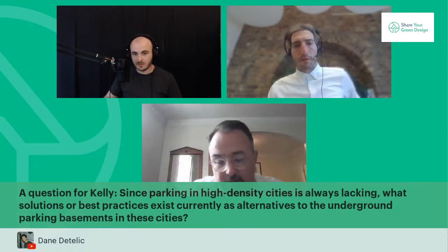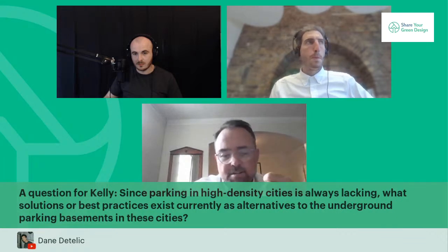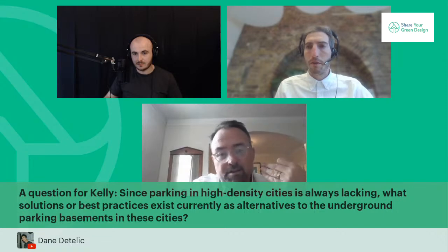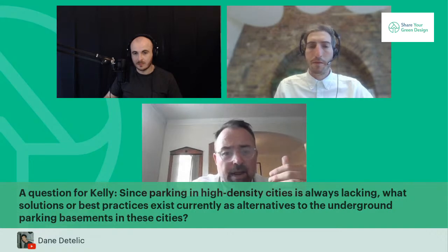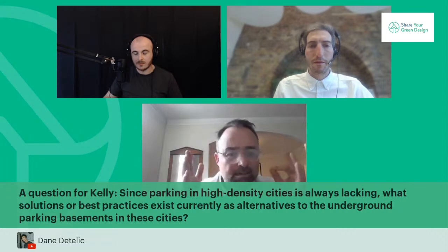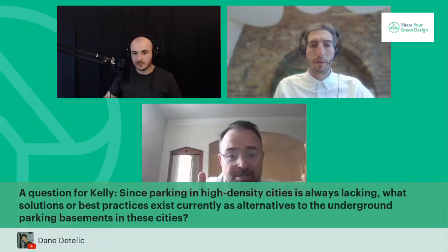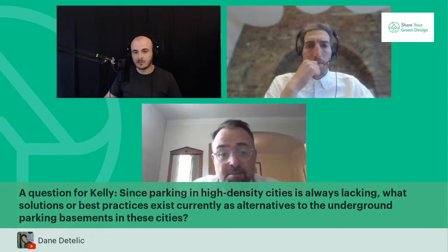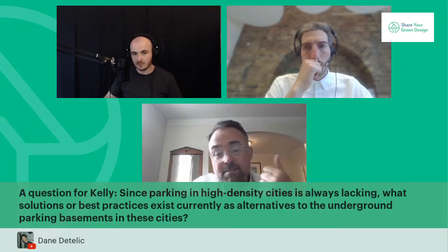That has dramatic reductions because your structure is about the same, but you don't have the retention wall, you don't do the excavation, and there's also a hidden kicker on this, which I didn't speak to, which is shoring. Any big hole has to have all the shotcrete and the horizontal piling to even keep the hole open before you can even cast the structure in it. I did the numbers on that same parking lot that I showed you, with that 1 meter transfer, and that was a 10% uptick on the building structure, just the shotcrete. So put it above grade.